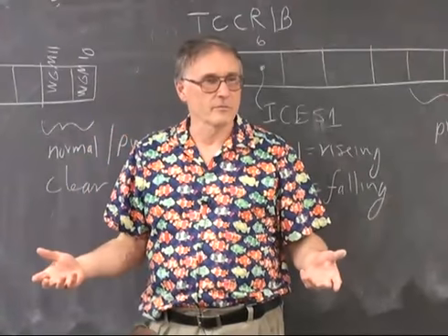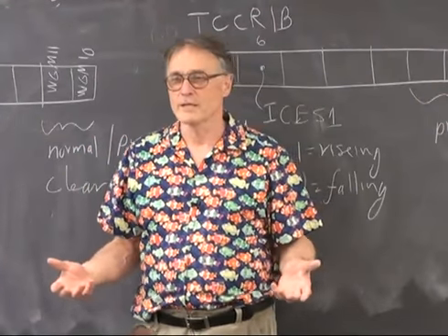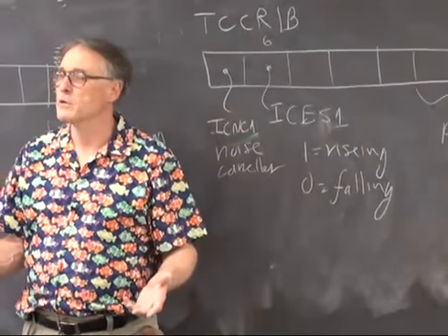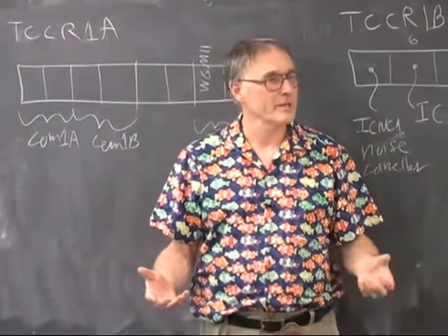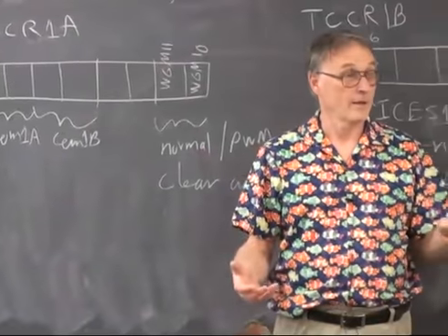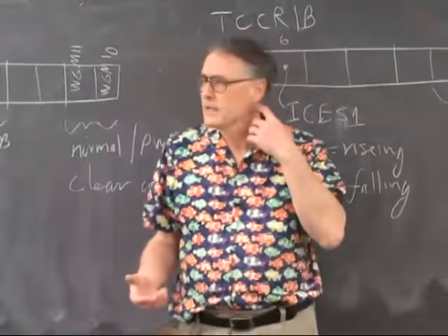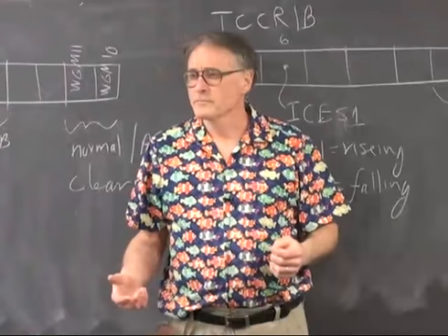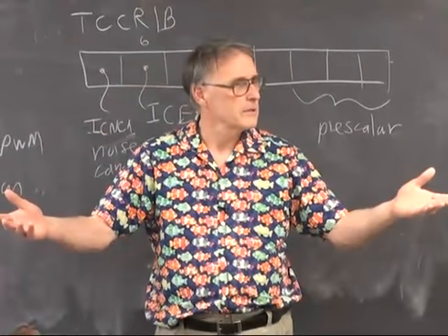So you know what Fourier transform is? It breaks down things into orthogonal sine waves. Fast Walsh transform breaks signals down into orthogonal square waves. It's ideal for a microcontroller because there are no multiplies, and there's no complex arithmetic. Think about it. Any questions? Any ideas for final projects?